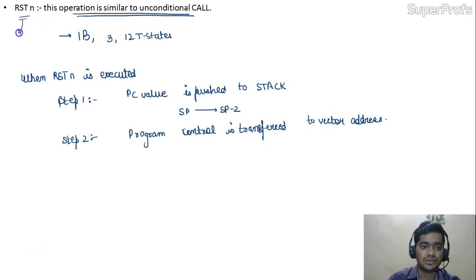Whenever an input output device requires the service of the processor, it requests with the software interrupt. In other words, whenever there is a program and an input output device requires service, it jumps to that separate program, the ISR stored for this RST, to provide the services of the processor to the input output devices.